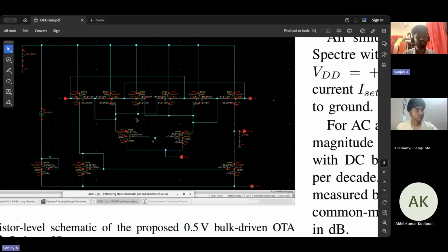Why 0.7 specifically? Because PPF is fundamentally a controlled instability. If M approaches 1, the negative conductance cancels all positive conductance, output impedance goes to infinity, and the circuit oscillates. You want M high enough for significant gain boost, but low enough to maintain stability and tolerable sensitivity to transistor mismatch. At M equal to 0.7, the gain boost is substantial while the circuit remains well behaved.